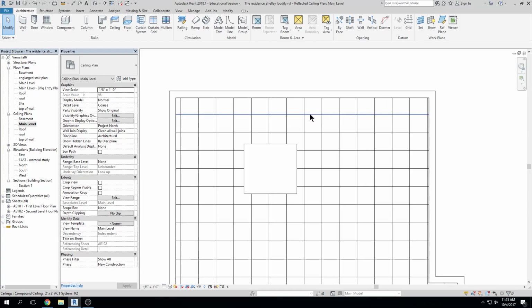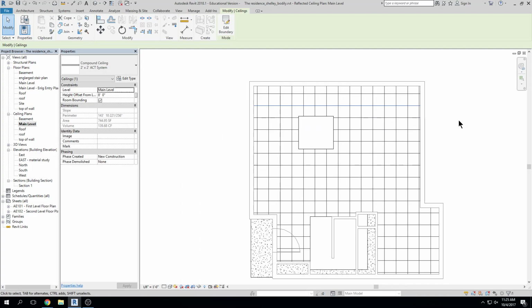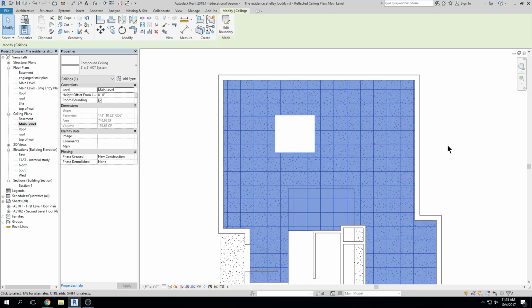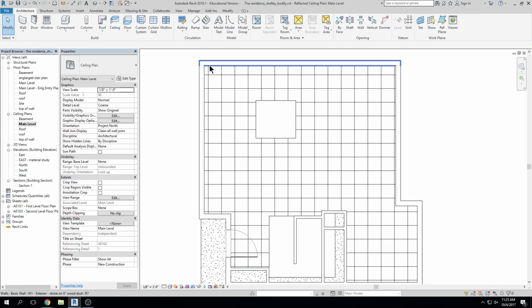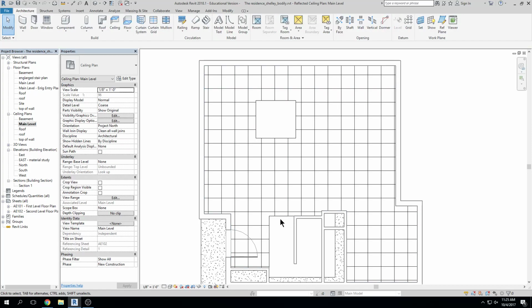With this, you can move the lines of the grid to make them how you want them. If I come near the boundary, I select this just like I would a floor. It is more easily selected when I approach an edge. Same thing with the floor. It was hard to pick the floor without a pattern. But if I go near a boundary, I can tab till I get my ceiling, and there it is.